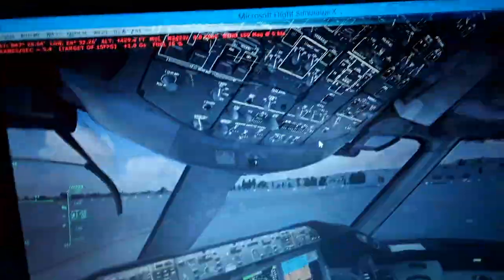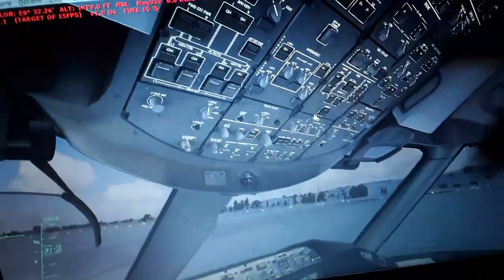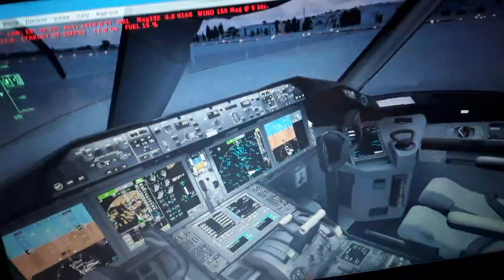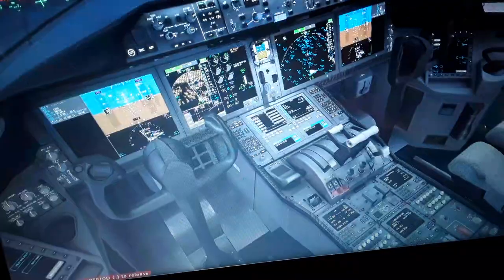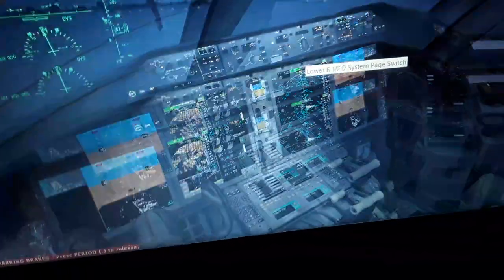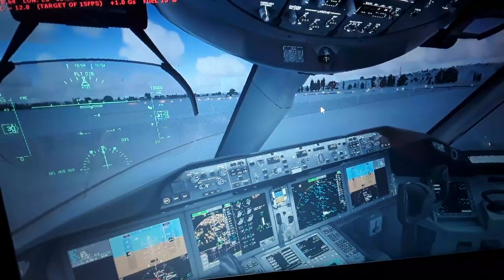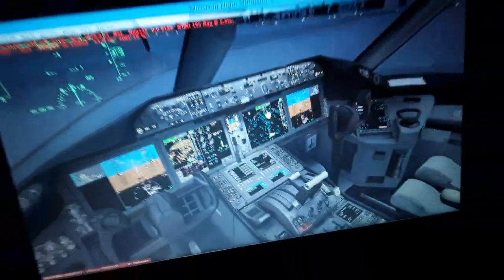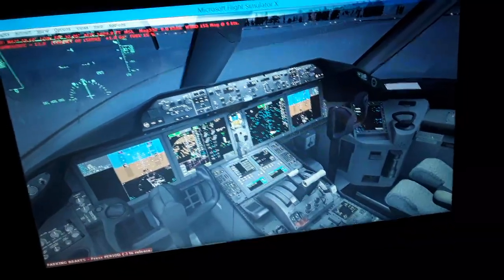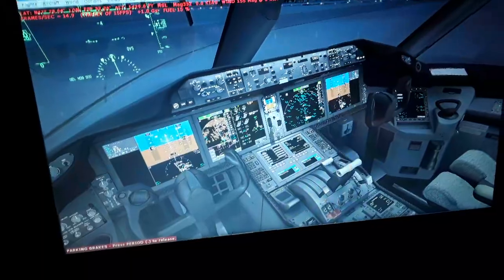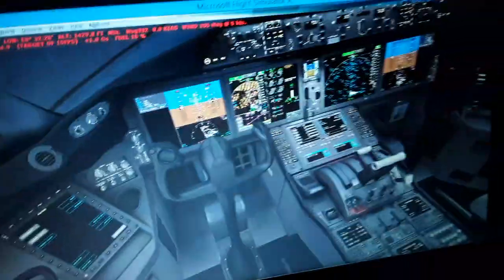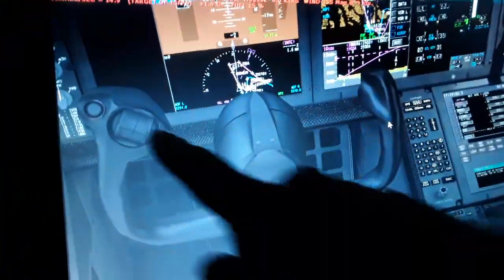If we have a failure of the L2 and R2 or either one hydraulic system, we can disconnect either elevator, left and right, horizontal stabilizer, horizontal tail from normal to cut out, and we can have the auto trim function disconnected from the autopilot flight director system panel, because we have automatic trim from the fly-by-wire system, flight management computer, in the auto throttle, flight director, and autopilot. So we're gonna use only the manual trim switch after.